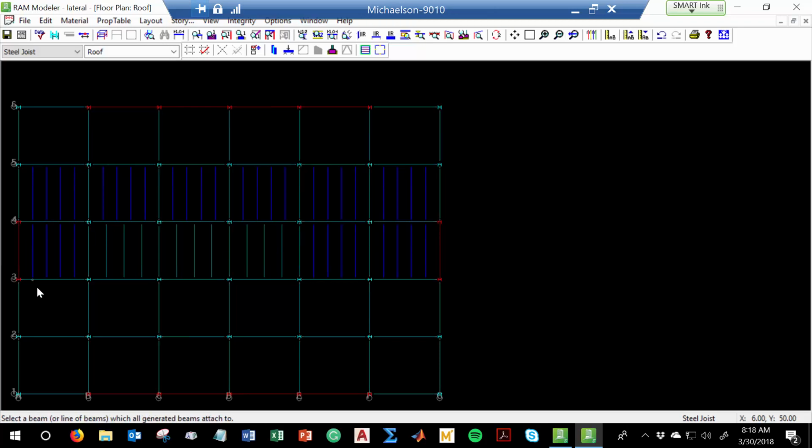Why am I using beams in these center 3 bays but joists everywhere else? That's where the equipment is and so on and so forth. So what I'm getting at is you can specify where you're going to use joists and where you're going to use beams. You can also specify your different loading scenarios. For instance, I can create a 100 PSF non-reducible live load and just apply that in that little square and then apply a 20 PSF snow load everywhere else or what have you. You see what I mean? So you can specify that accordingly, and I wanted to show you that that's an option.